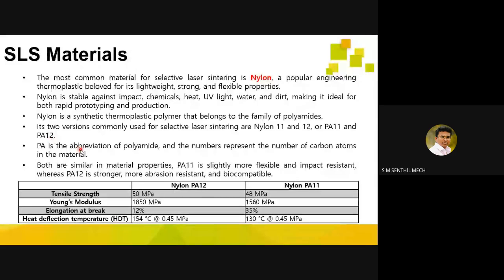Both PA11 and PA12 are similar in material properties, but PA11 is slightly more flexible and impact resistant compared to PA12, whereas PA12 is stronger, has good abrasion resistance, and is biocompatible. Whenever you're talking about biocompatible, yes, it can be used for biological applications.